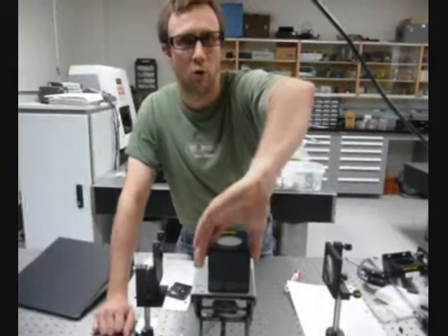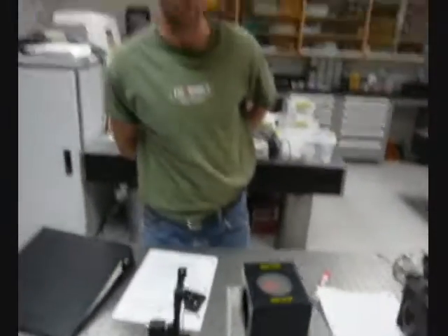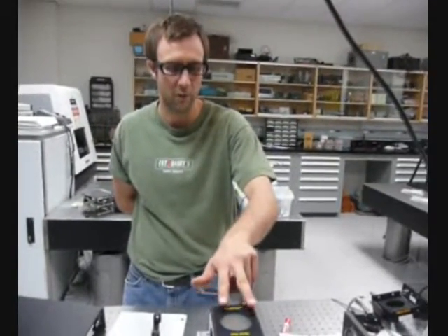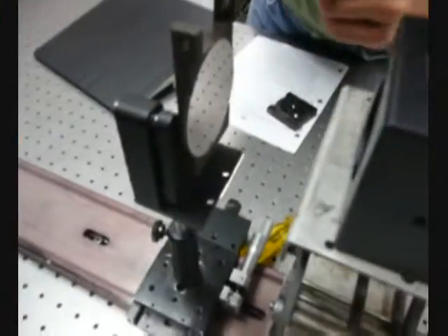So we're going to rotate the cube 180 degrees. And you'll now note that we can see the mirror surface. And we can take the angle and the S number off of this by measuring the shear distance and measuring the angle of these fringes. We can go back and calculate what the focal length of this mirror is. And you can kind of notice that if you see here, they're pretty rough looking fringes. And part of that's because the mirror is not a very high quality mirror.